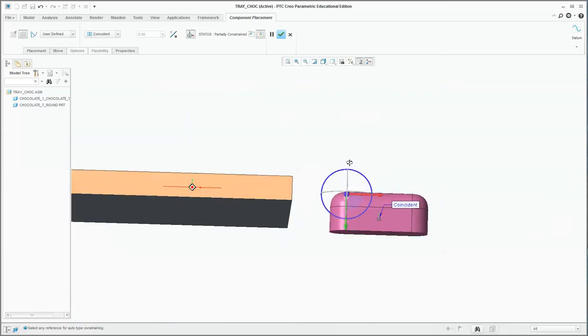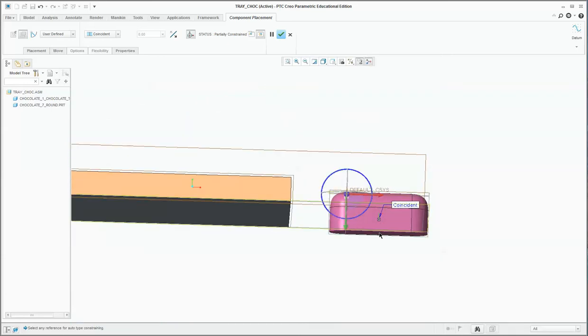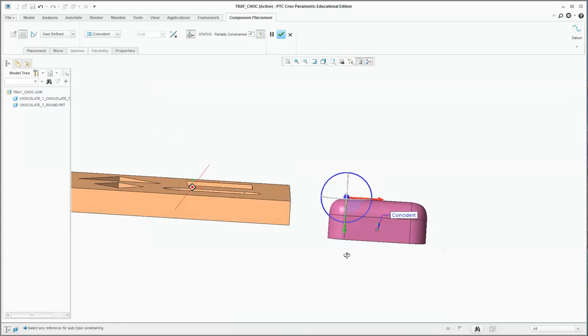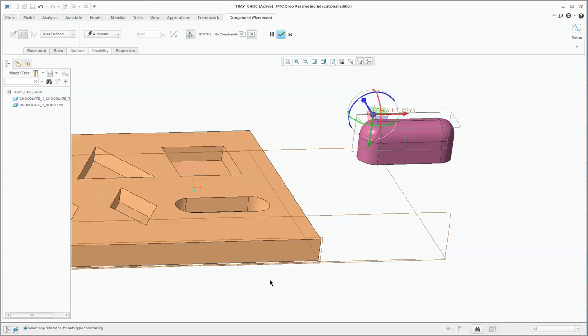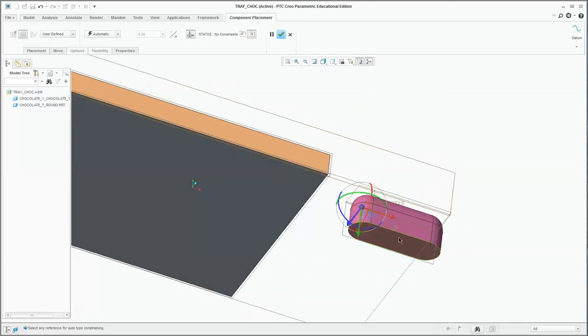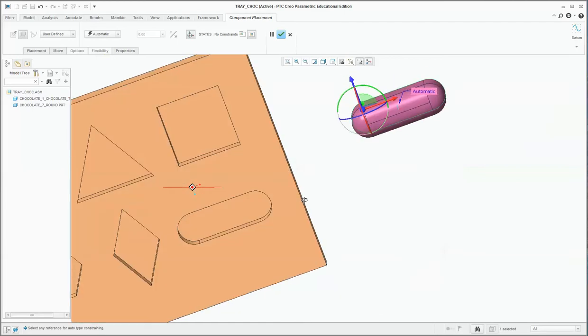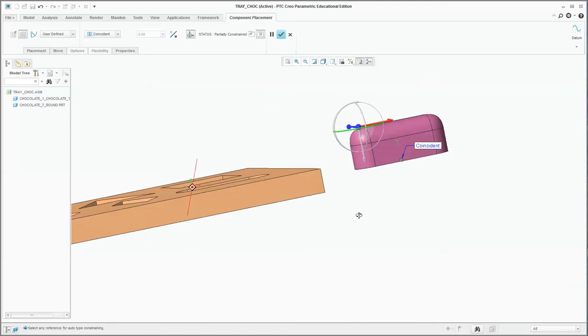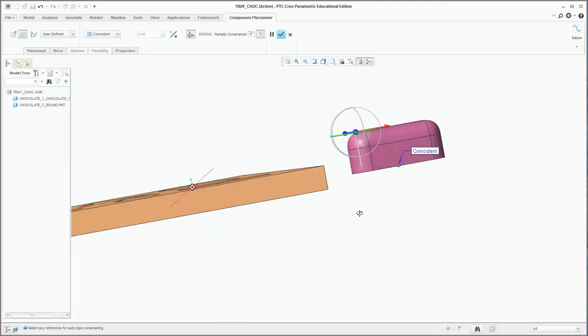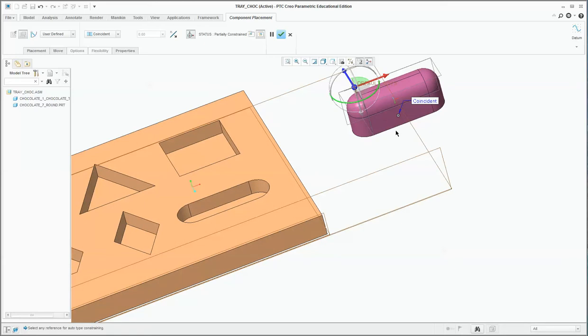And if you actually look here, our original base we had that was flush is no longer actually flush. We've actually sort of wrecked it by choosing our incorrect surface. So this can happen to you a lot. So it's very key. If you want to remove and undo what you've done, you can start again very easily. Just right click, remove those surfaces and put them back. So let's line them up. It's looking flush again, that's looking better. Because remember, it isn't flush to the base, it does sit partly in a little bit to the way that it looks. Now let's move on.